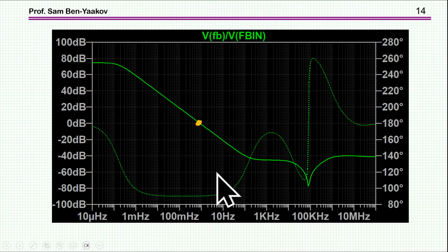And here is the loop gain. As I have said, there's no attempt to have a wide bandwidth. In fact, the crossover here is at, what is it, like 1 hertz. It's okay. We are interested in this region here. Crossover is at 90 degrees, so it's a fairly stable system in terms of stability, oscillation, phase margin. However, it's a slow system because the bandwidth is only 1 hertz, but we don't care about this in this